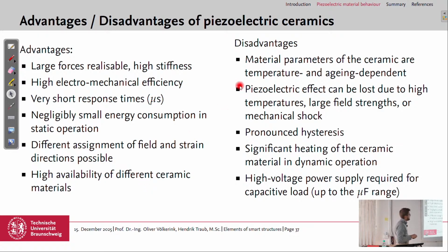And disadvantages are the temperature-dependent behavior. Even in the, let's say, normal temperature range, it's not negligible. We can lose the piezoelectric effect due to high temperatures, the Curie temperature, due to large field strength, so going above Emax, and also due to mechanical shock.